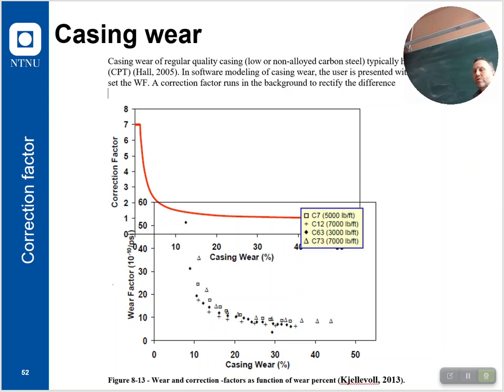Basically, what you're coming down to is to run wear logs like caliper or wall thickness logs to understand, yes, it works. My presumptions were good. Still, believe it or not, the industry uses the wrong calculation. They use regular casing wear calculations for 13% chrome, and when they back calculate, they get wear factors ranging from 5 to 50, right?